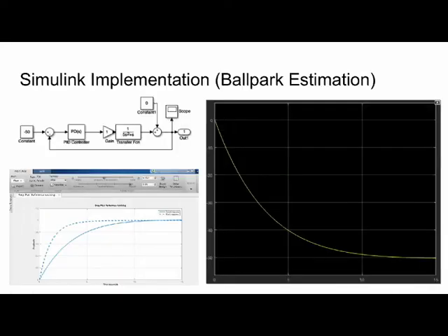I'll now let Matt talk about how we optimized our PD controller. To test the system, we put it into Simulink with a fall height of 50 meters. Our model doesn't include gravity as a disturbance because it is constant. Our system outputs force relative to the force needed to hover.